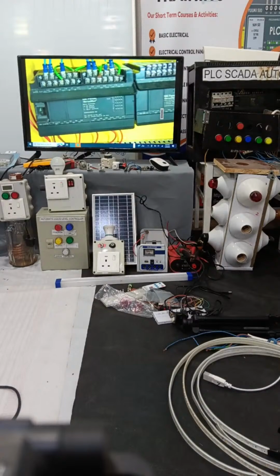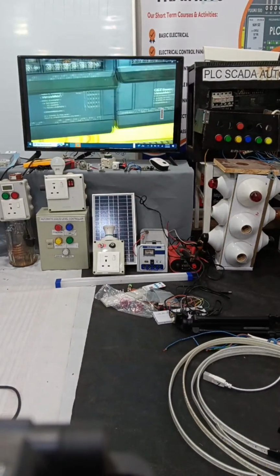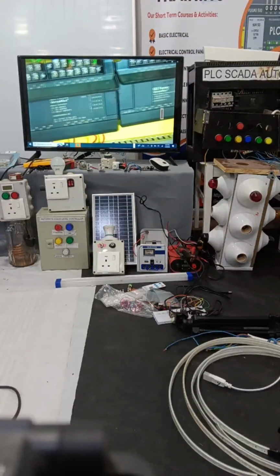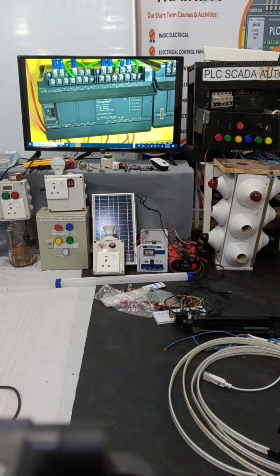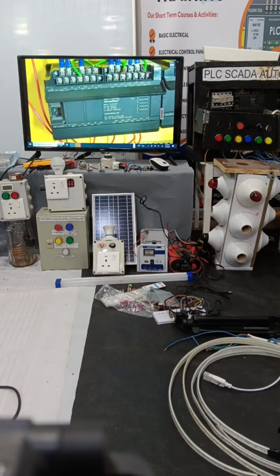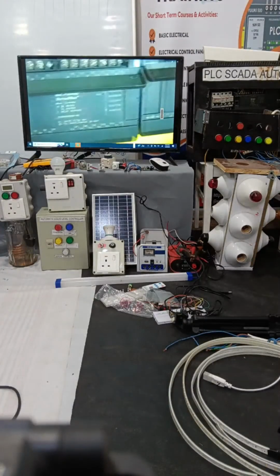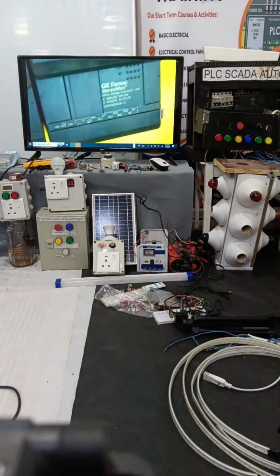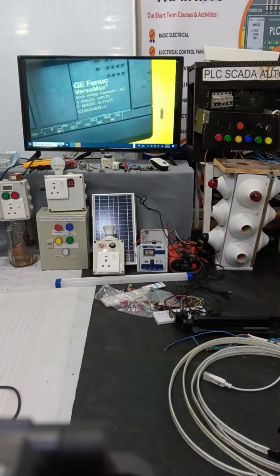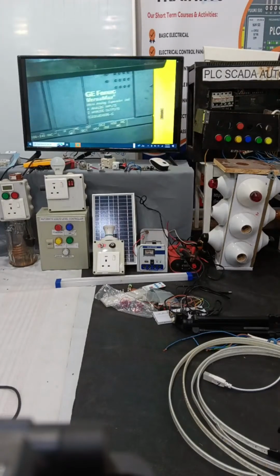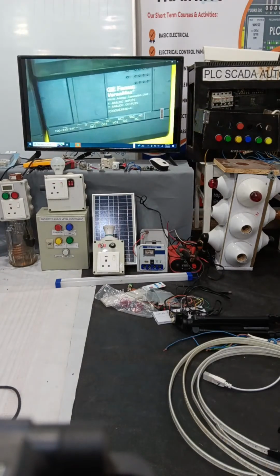As we discussed, this is known as a programmable logic controller or PLC, which is the heart of the system. The first module is called the CPU, Central Processing Unit, like a computer. It processes the data. The second one is the extension module. There are two types of input output. One is digital and another one is analog.